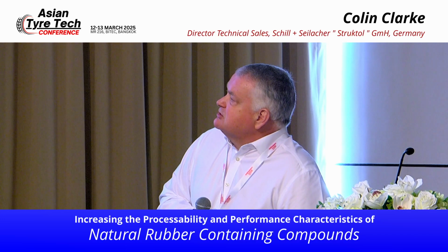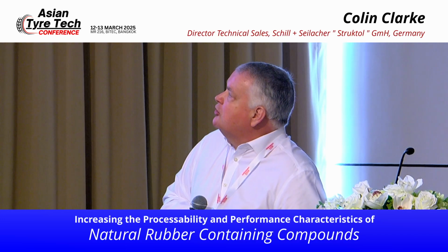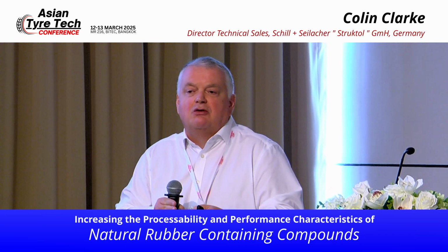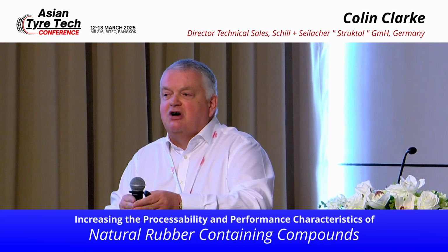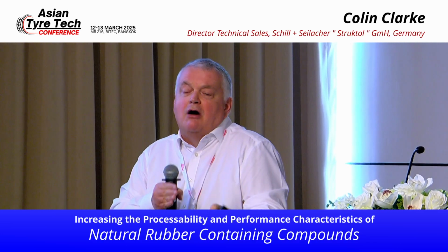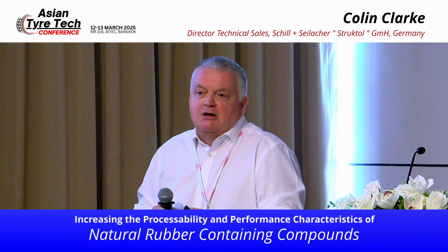And we can, so we take the same compound, and now we're going to do mixing and carbon black addition in the same stage. So we start with natural rubber, we add the peptizer fairly quickly, we add the carbon black, and we finish the compound only in 2 stages.